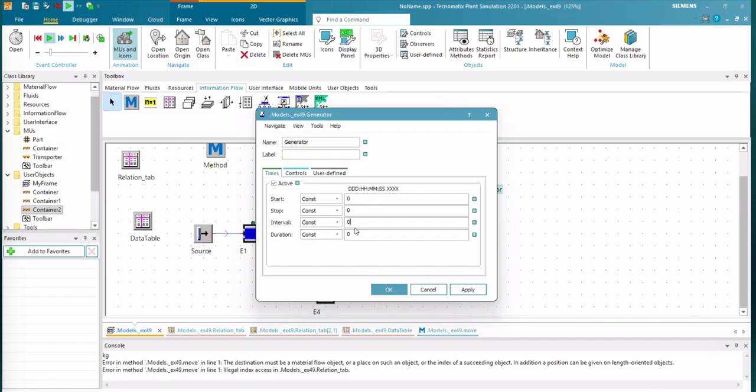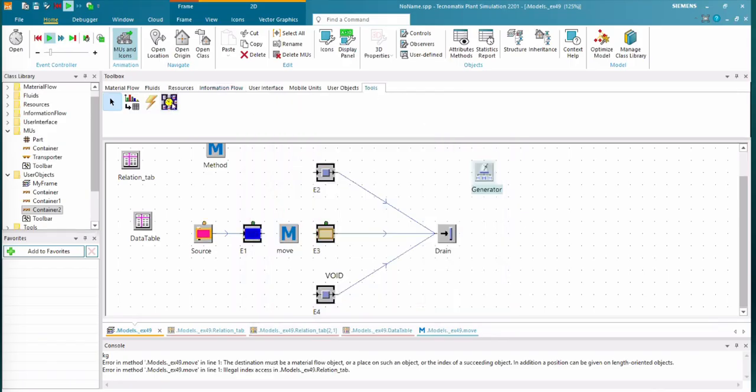And to deal with the stochastic model, you need to run your simulation model several times. And how to do it? You do it not by clicking the reset button and play button several times, but you can do it with the experiment manager.